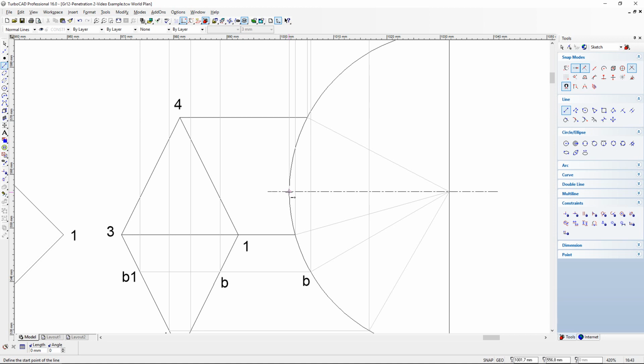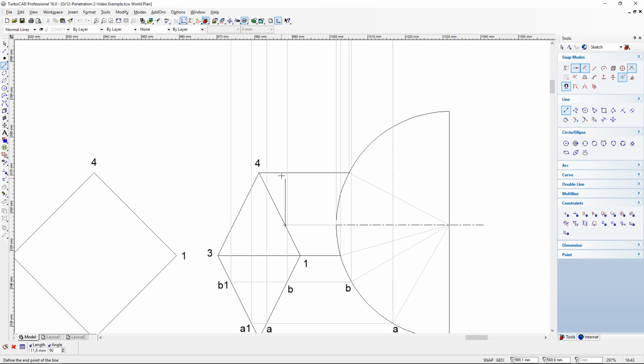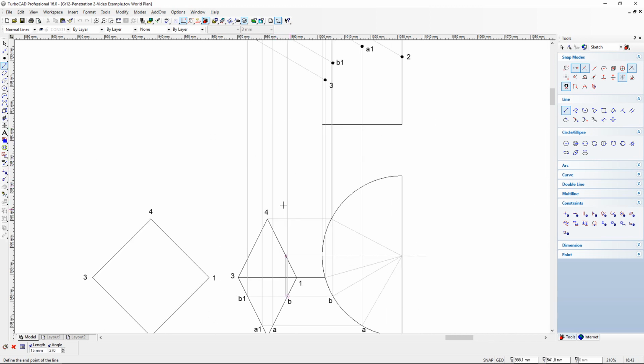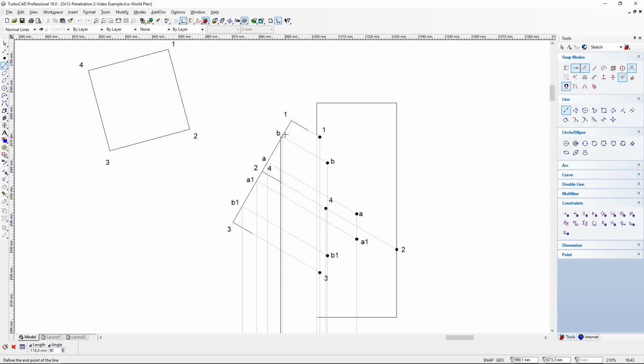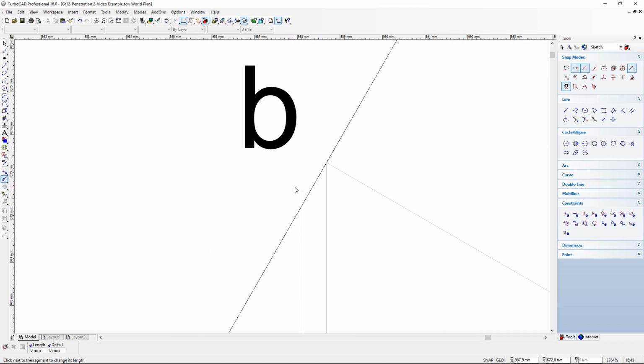So I'm going to take this point and I'm going to draw a horizontal line now onto our prism, and then from there I just want to quickly make it there right to the edge, and then from the edge I'm going to draw it straight up. So I went to number 1,4, and therefore it will be number 1,4 here on the front view, and I make sure that it is hitting the edge right there.